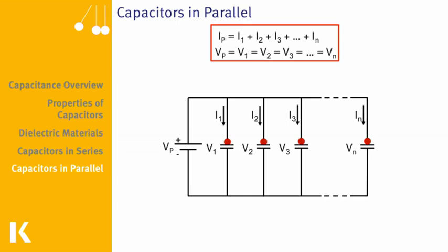As with capacitors in series, both of these rules are the same for parallel resistors and parallel capacitors. Equivalent capacitance, then, is the one that is different, resembling the method for calculating equivalent resistance in a series circuit. That is, the additive method. Here, notice that when more capacitors are present, the equivalent capacitance goes up.